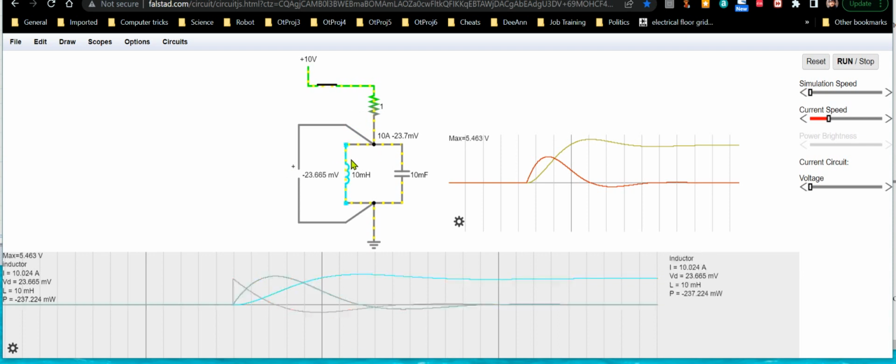but it'll allow frequencies less than that to pass. For example, a 1 hertz frequency would mostly pass through the inductor, because at 1 hertz the inductor will act like almost just a piece of wire. It'll have very low amounts of voltage across it. In fact, it'll allow DC to pass, like you see here, with 0 volts across it. The capacitor will block DC. That's why it doesn't have any current flowing through. You can see the little current dots aren't moving at all here. So it'll block DC,